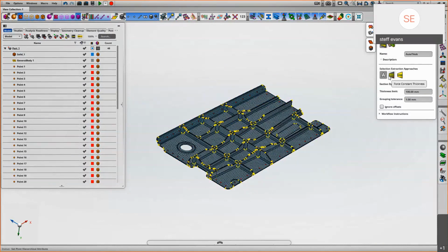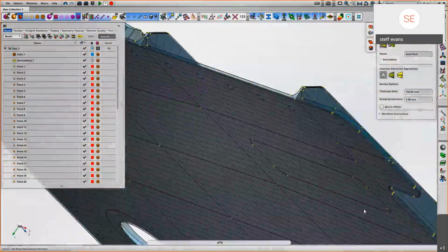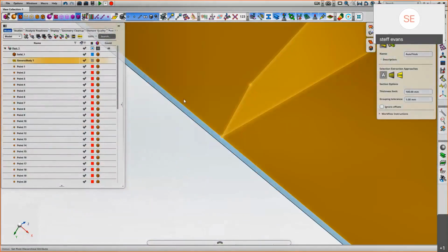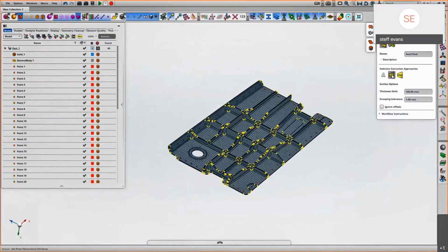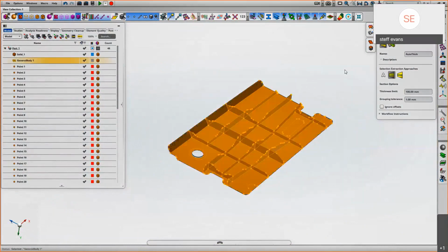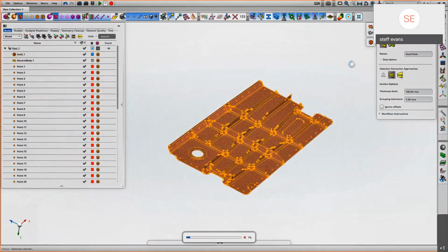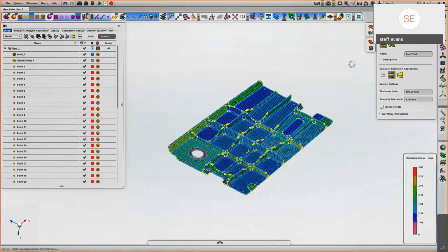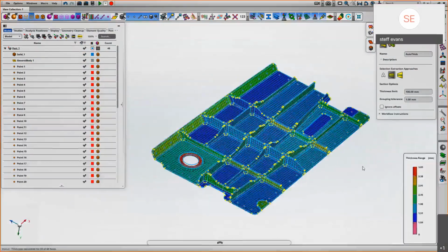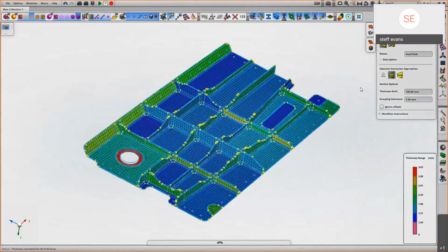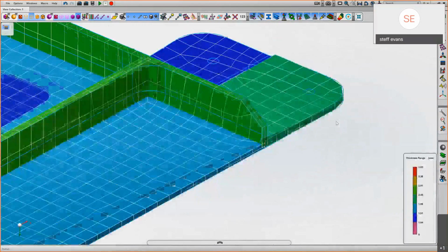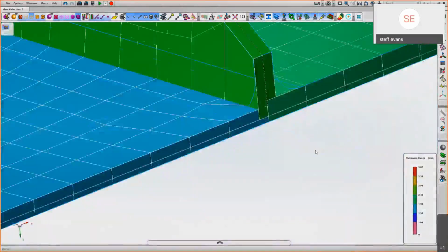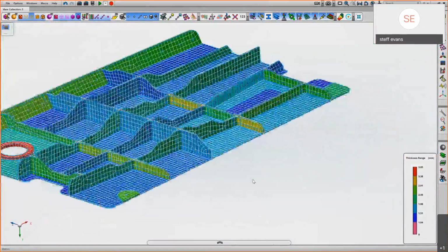And so we're going to force a constant thickness, so we don't get steps where we've got the local fillet section changes. That could give us a very messy model. If you did want to look at fillet section changes, you'd probably want to be looking at a 3D model. So by forcing the constant thickness, it does simplify things quite nicely. So pick the face, pick the solid, and generate those properties. You can see there very nicely how they're generated. Turning the shell thickness on, and with the 3D solid in transparent mode, you can see how well it's done mapping those shell properties across.